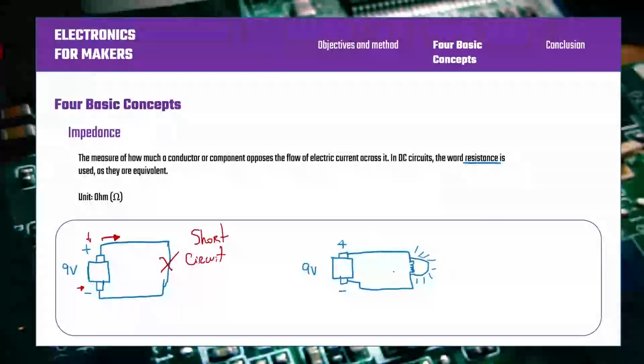So this brings us to what we call Ohm's law. Ohm's law is basically that the voltage equals the resistance, the impedance of the circuit or component, times the current that passes through it. And with this definition, you can go to the other formulas. You just rearrange the variables. This one is to find the current, I is the current, and this one to find the resistance. So you see in this formula here, the second one, I equals V over R.